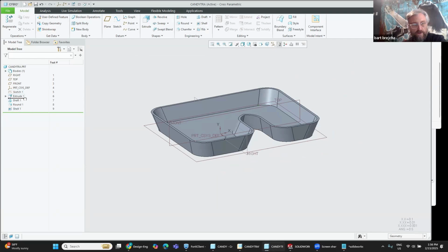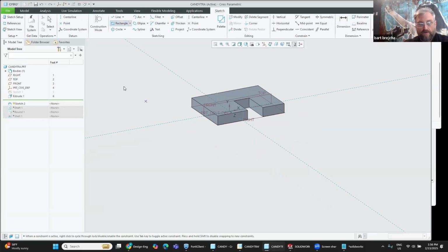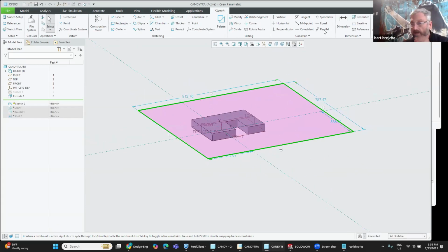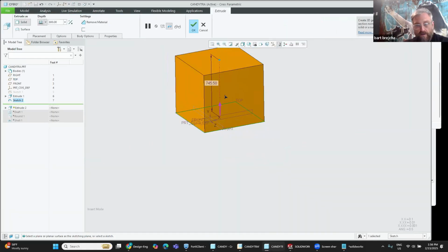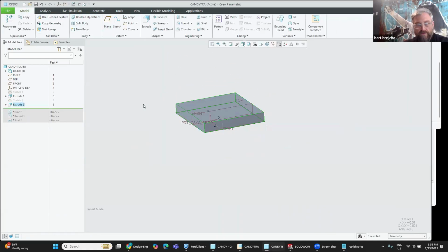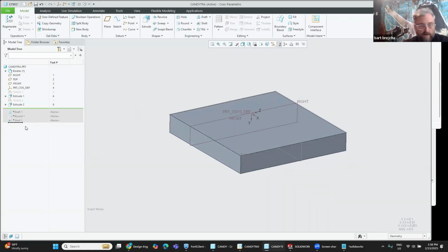So what I'm going to do is go here to this first sketch and then draw the mold base. Tray works too. All right, whatever big, however many cavities in the mold there are. So this is the mold base. All right, and there's the draft, the rounds.